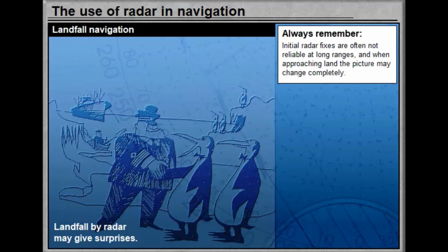The position of the reflecting surfaces of the individual targets are changed with respect to the antenna position whenever the range is altered, and pulses are more favourably or less favourably reflected. Sometimes this is observed as an apparent movement of land towards the observer, as the lower parts appear above the radar horizon.